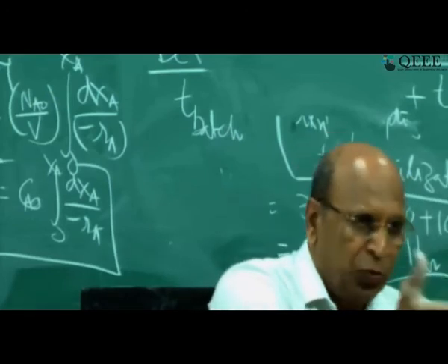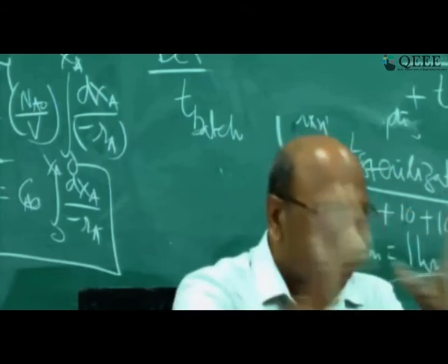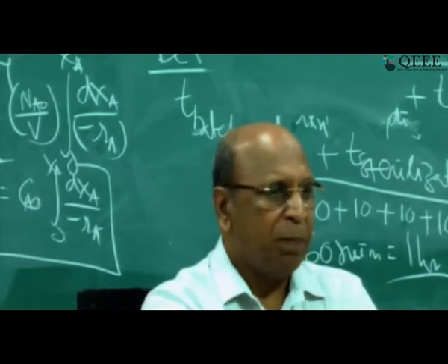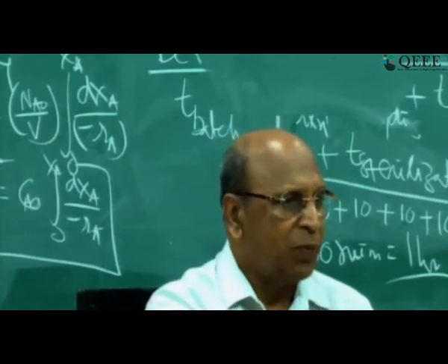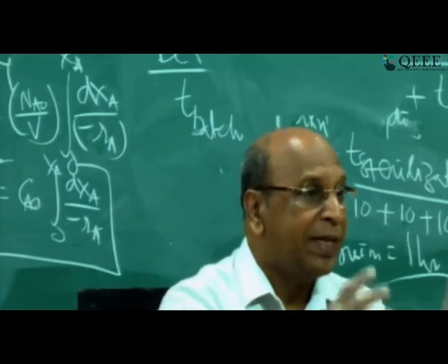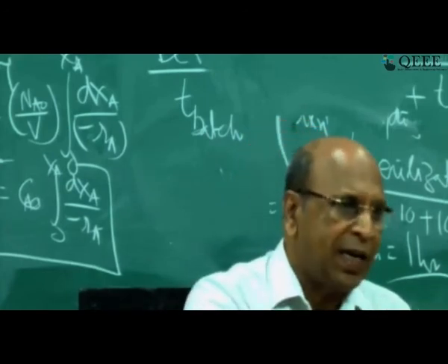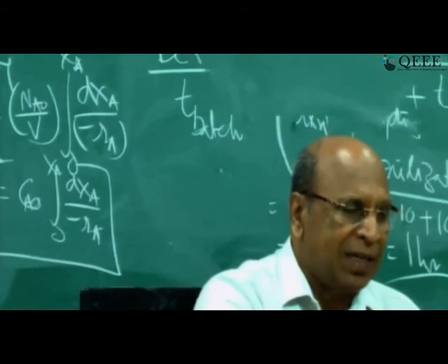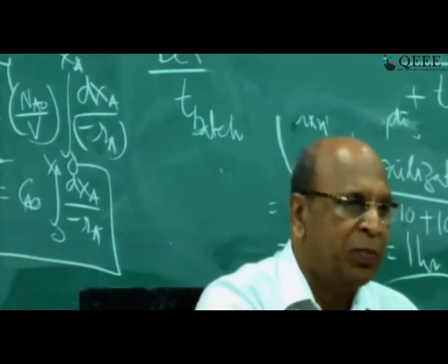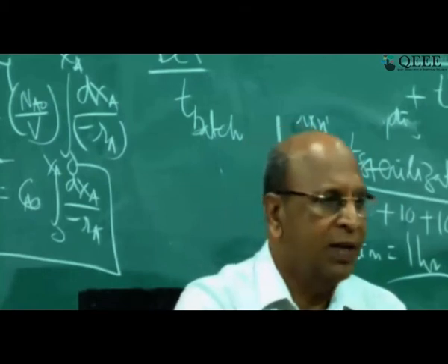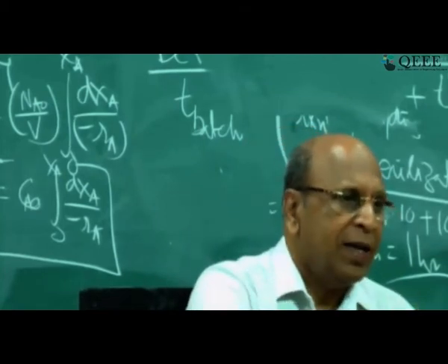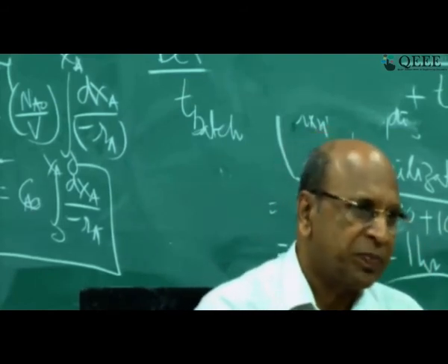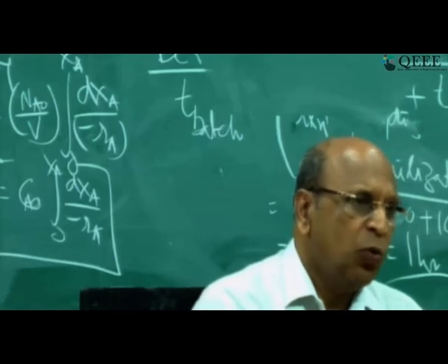And if you look at biochemical processes, all of them are using only either mixed flow reactor, what you call chemostat, or batch reactor. The reason is it is very easy to provide that much residence time in tank reactors. But in a plug flow reactor, to maintain plug flow and conduct the reaction, to provide the residence time is very difficult because the length is very long. That's why it is a very good question. PFR can be used if the reaction time is very small, normally in minutes. And a tank reactor we can use, I think, even hours.